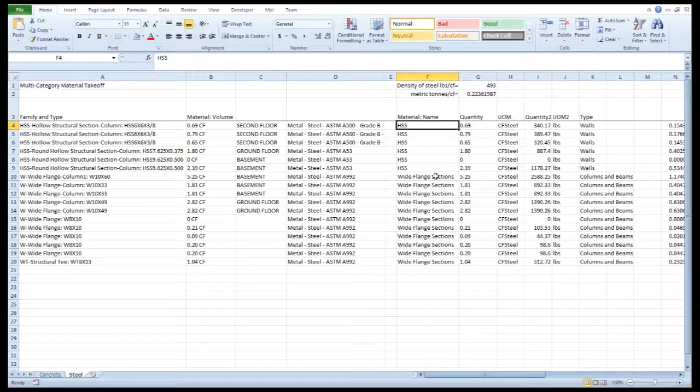If you know that in advance, it can be an advantage. So I've chosen it here just to show you what happens. A couple other things, we've got a zero quantity in a couple of places in our quantity column. Unit of measure, again, we had to separate between numbers and units of measure, and I've called this CF steel instead of just CF. And the reason for that is that one of the problems is that the CAD program has exported a volume of steel, but the data in the